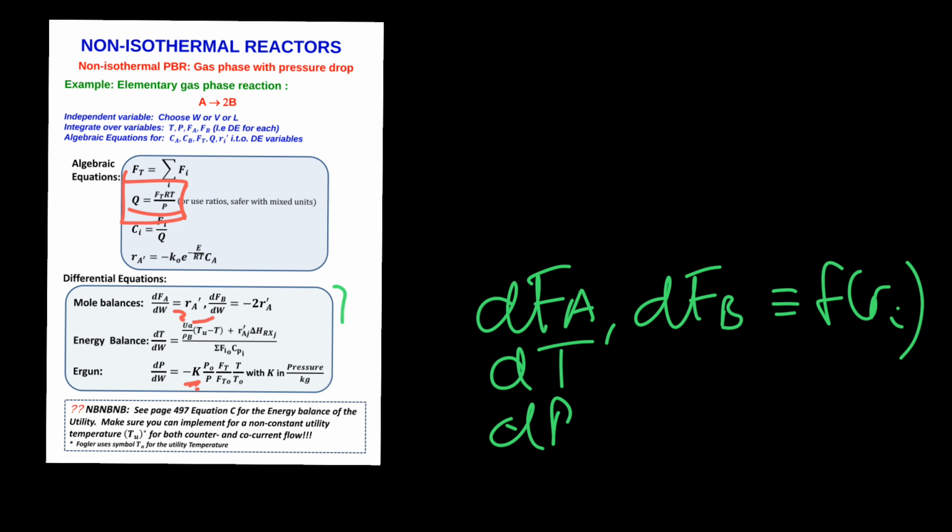If I now go into my equations, once I've now written them down, look at, do I need parameters, define them outside or calculate them outside of my function. UA, I will calculate the heat transfer, overall heat transfer coefficient. What is the A value? Remember the A value directly related to inverse of the diameter of my tubes. Concentrations I can calculate, but Q will vary because it's a gas phase reactor, and it's going to vary according to the ideal gas law.